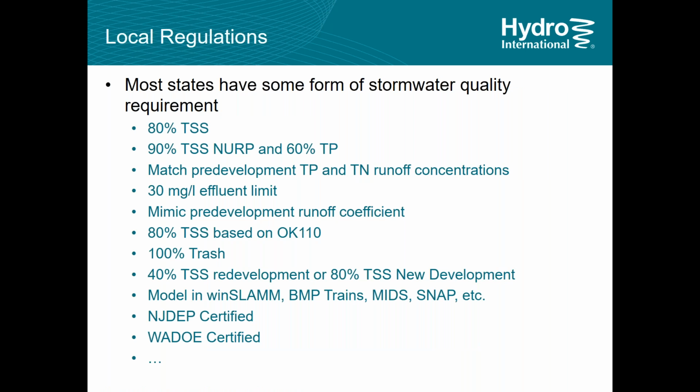So, local regulations. This is another problem we have in the industry when we come to developing equipment. Everyone has a slightly different idea of what they want. Traditionally, the rule was, oh, we want 80% total solids removal. And then some people started looking at the total solids and going, really, we should define that, because is it 80% of sand? Is it 80% of silt? Is it 80% of gravel? They're all correct. But what is it?